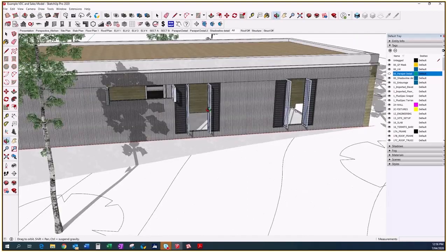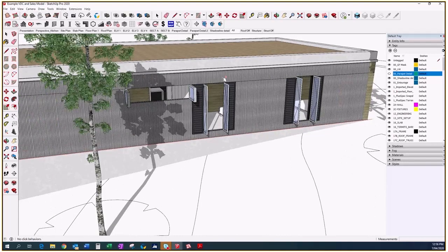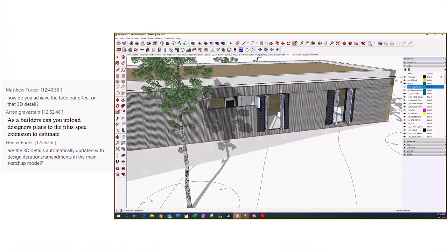And more importantly, with SketchUp, this is essentially just a dynamic component. You can recreate it in a similar way. The advantage of dynamic components is you can cycle through, for example, different size beds. You can open and close things so that you can understand if there are any clashes.